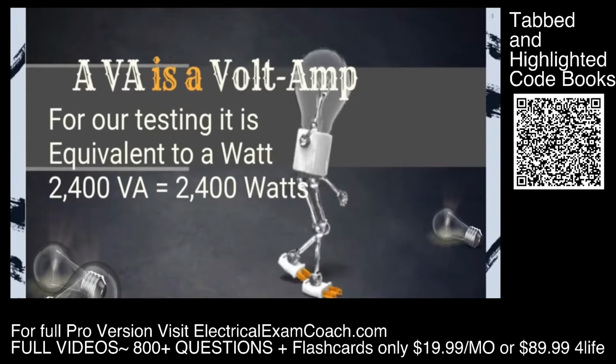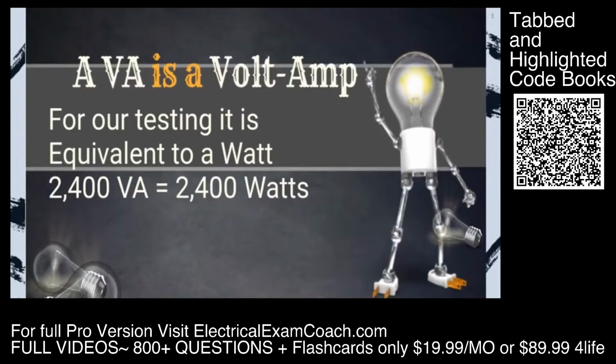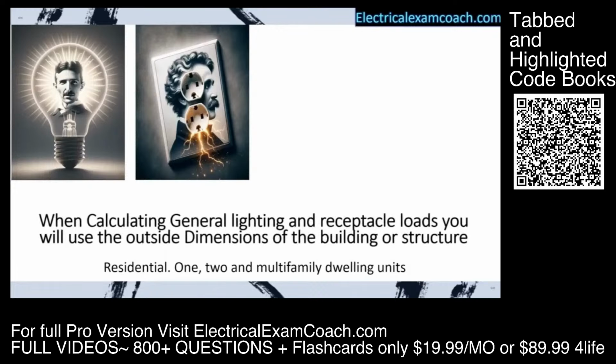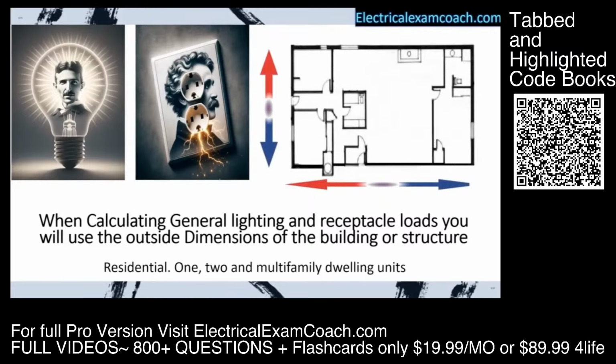So it's true for us to say that 2400 VAs is equivalent to 2400 watts. For these calculations, we're going to be calculating them at 3 VAs per square foot. When calculating our general lighting and receptacle loads, we will use the outside dimensions of a building or structure. So we're going to measure from the outside of the building, both directions, do our multiplication, and that'll let us know how many square feet we have to multiply by.